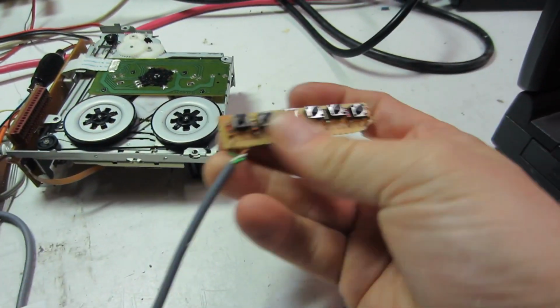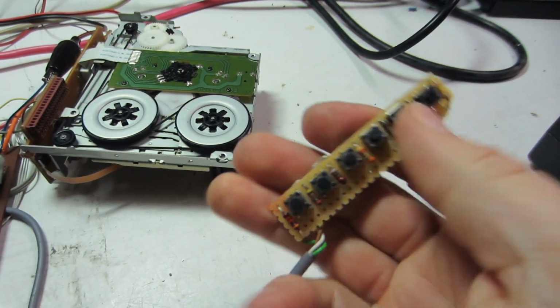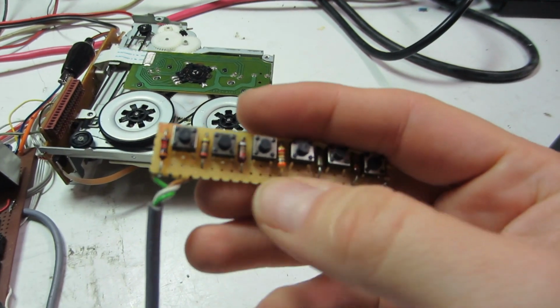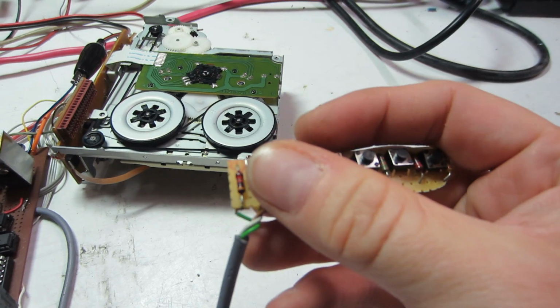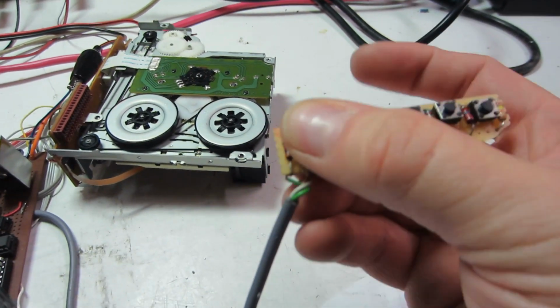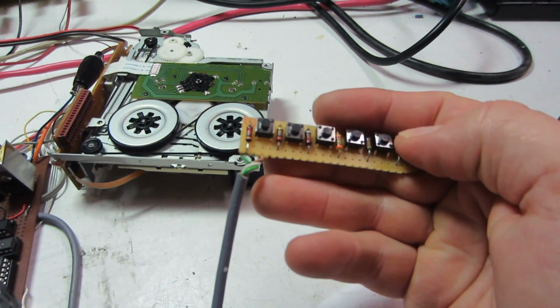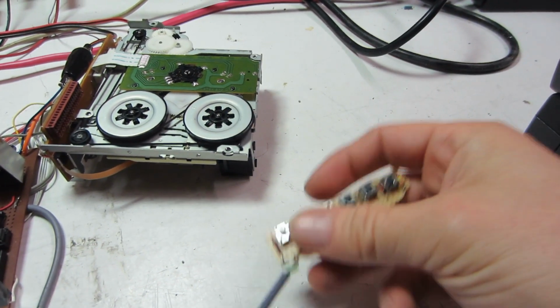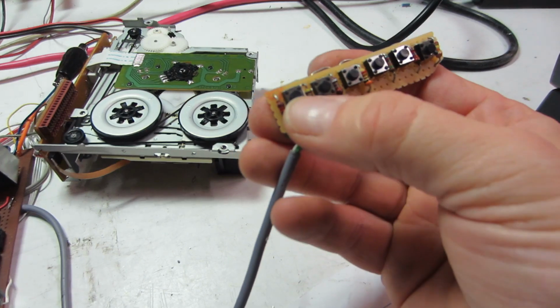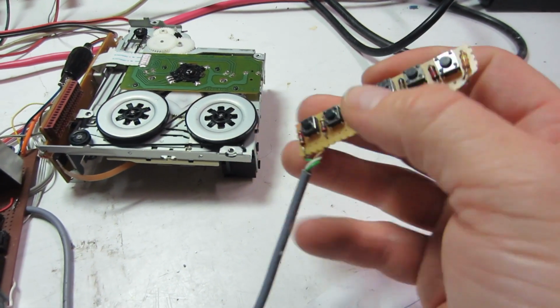So next thing is I wanted to save as many I/O as possible to implement more features. So one of the things I did is I hooked the buttons up to an ADC input through resistors. If you're designing electronics, this is pretty much a no-no. So many makers of cheap audio equipment, for example, do it like that. They cheap out.